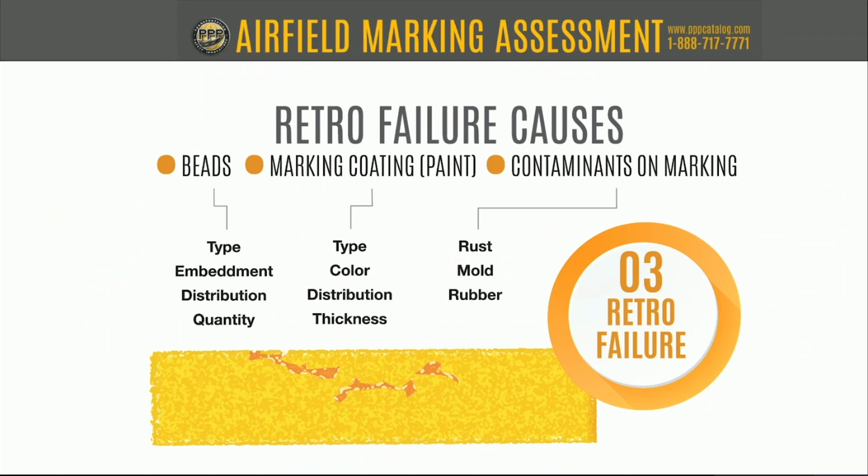The other thing that can directly cause either one of those things is the uniform thickness of the material that you're applying. 99% of the time, I'm looking at waterborne paint. So if you are spraying maybe a 6-inch line or 12-inch line, one gun, and it's not perfectly even, that will absolutely affect not only your retro levels, but your uniformity as well, or the lateral deviation, we sometimes call it.